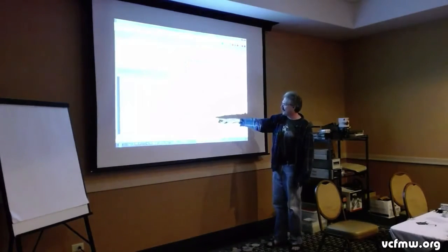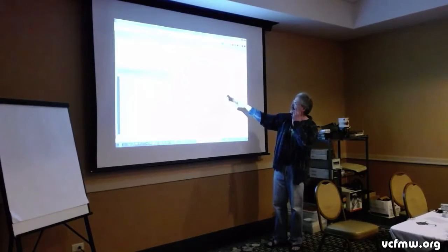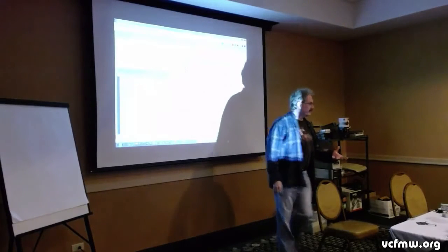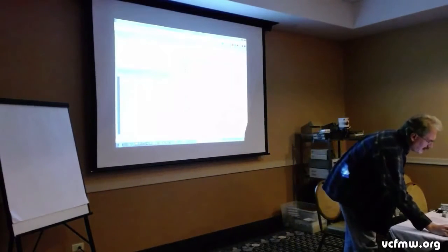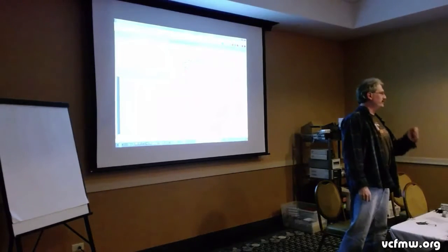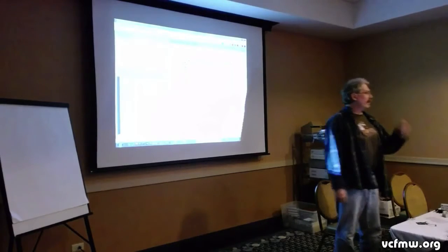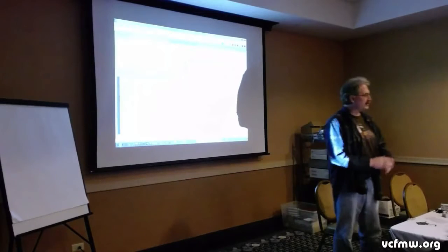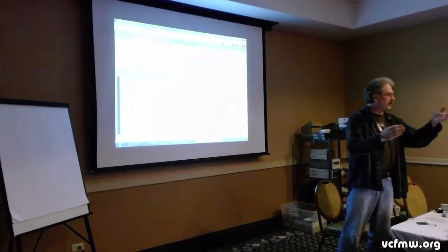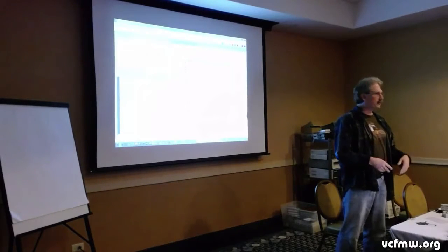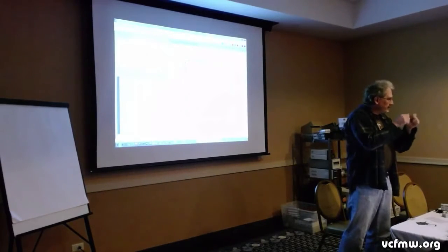Now the yellow, green, red, and pink boxes are special, but the ones that are just circles are ones that you get to use. All you have to do is drag these from one place to another, and you can change what pin is equal to what signal. I had it laid out to match the schematic, but then I realized on Friday that I had the 0 bit and the 1 bit messed up. Normally that'd be another spin of the board, right? Or I have to cut the traces and whatever.